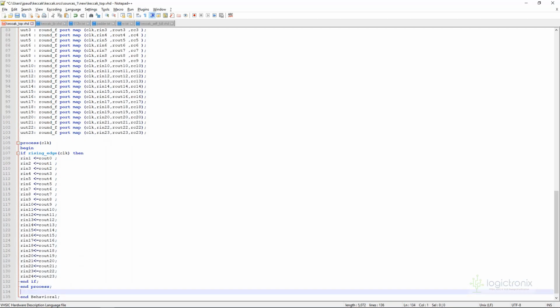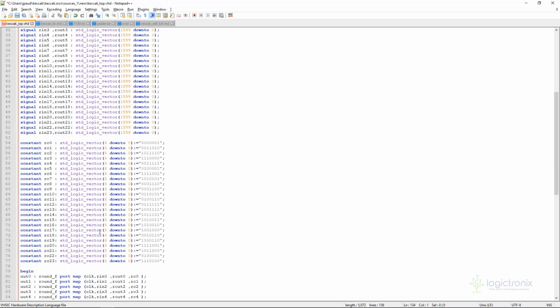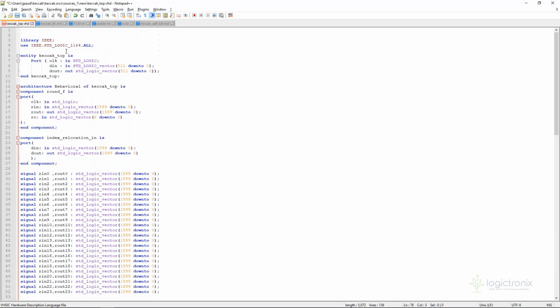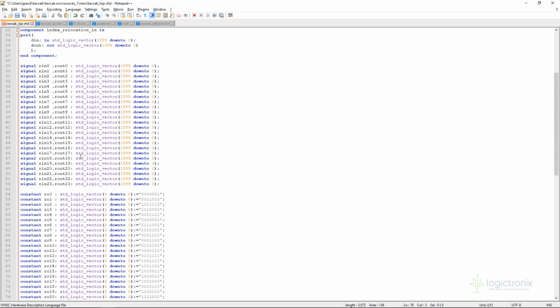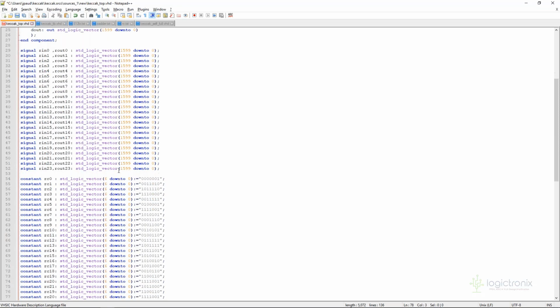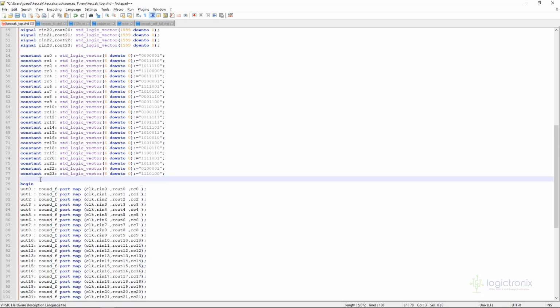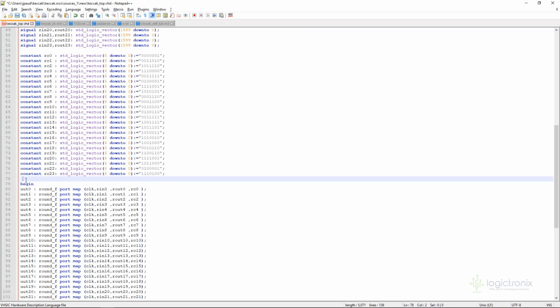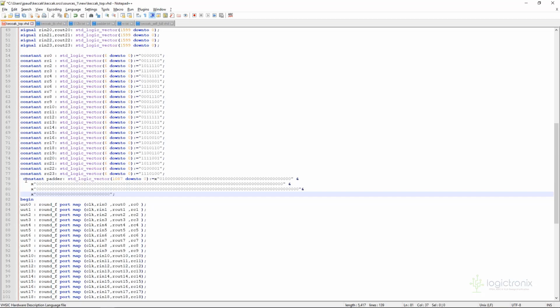So the Keccak is almost completed, but we need a little bit of extra things. The input here is 512 bits, but the state of Keccak works in 1600 bits, so we need to pad it before we pass it to these states. So I have got the padder. This is a constant. You can just paste it here. This is the padder, and we're good to go.